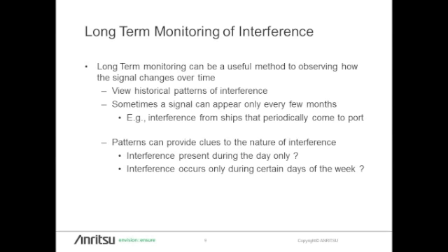So the other issue is it could be daily or weekly. Other examples we've seen, maybe an interferer just pops up on Sunday. We've seen this in one case where a church was using a wireless microphone, and every Sunday the adjacent network system was dealing with interference. So it gives you different clues to look at and patterns, so that even before you go out, you have some idea of what you're looking for and where you're looking for it.